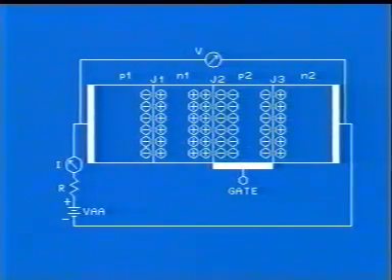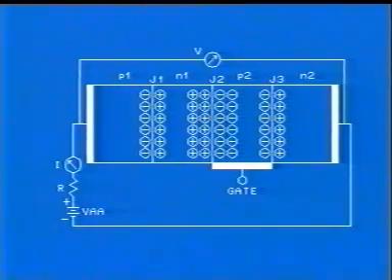As the anode is positive with respect to the cathode, junctions J1 and J3 are forward biased. Therefore, electrons and holes can cross junctions J1 and J3 easily. Say, two holes move from P1 to N1 and cross the junction J1.